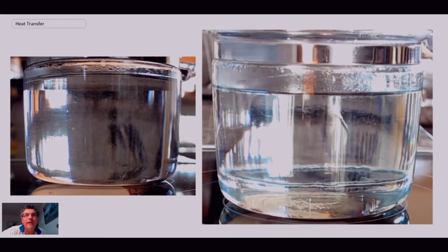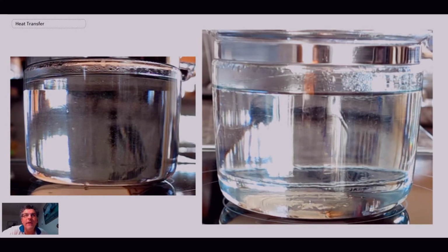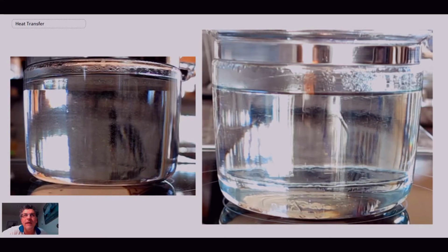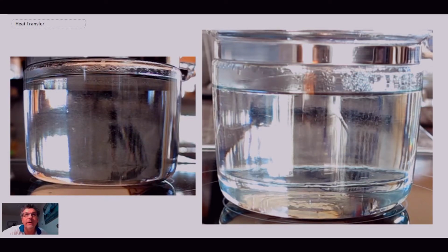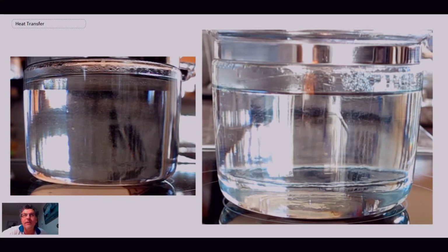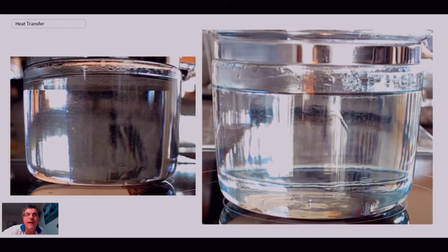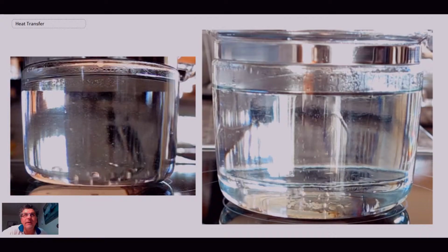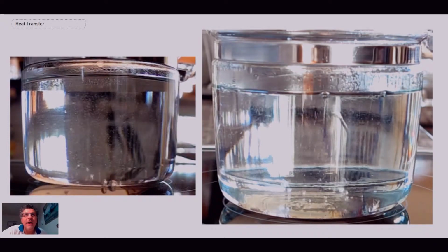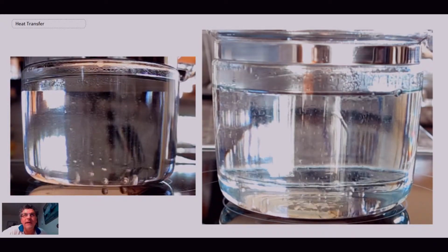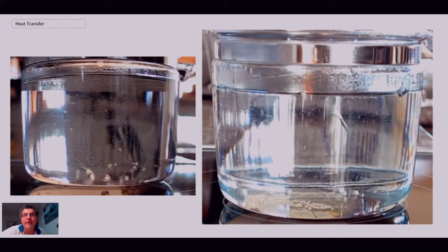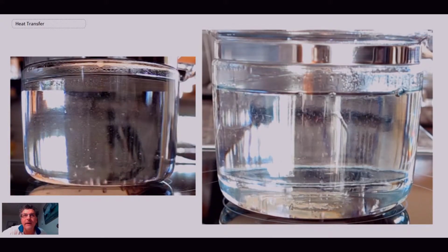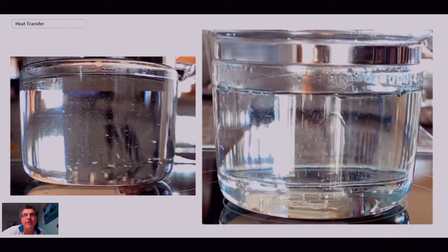And so what we can see are bubbles that are forming on the surface, and they're trying to move up, but the fluid is at a cooler temperature, and the bubble through heat transfer collapses. It doesn't have enough energy to make it to the top. And then some bubbles get a little further, so this is a little later in time. And you can see some bubbles ascending a little higher, but still they're collapsing. The pool temperature is not hot enough in order to sustain the bubbles going to the surface.